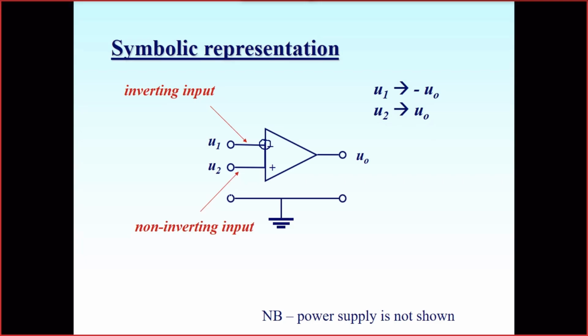In general, the operational amplifier is a differential amplifier with very high gain, nothing else. So what does differential mean? The output voltage is proportional to the difference between the non-inverting and inverting input voltages. This means differential. Generally it's a DC amplifier, and what else? Yeah, this amplifier has a very high gain. So this is actually its main feature.